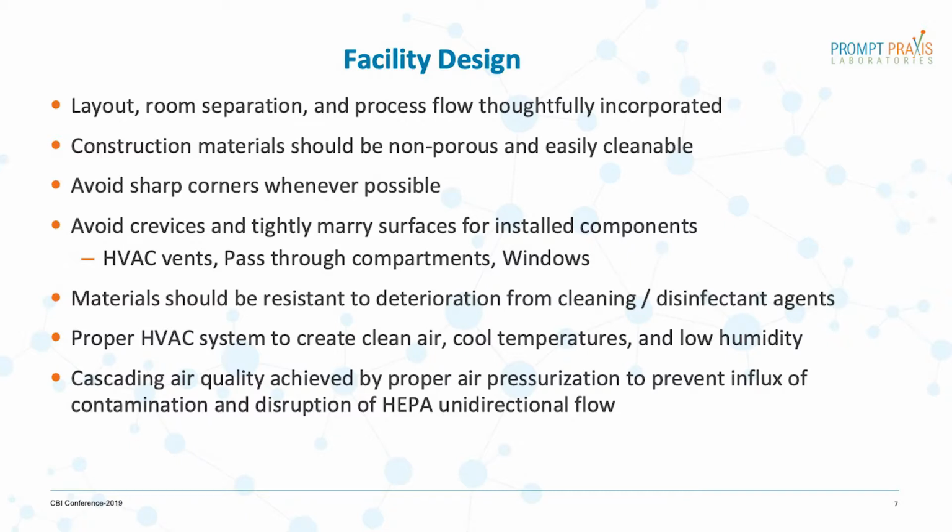and the humidity low. Clean air, you mitigate your introduction of viable and non-viable particles. You cool temperatures, you inhibit the growth of organisms if they do happen to be there. And low humidity also. The drier the environment, the less attractive it is to microbial growth. And then finally, the concept is you want your cleanest area to have the highest quality of air, and then as you move away from that, you want the cascading air quality to be achieved on an inward to outward basis, and achieved typically using HEPA filters and unidirectional flow.